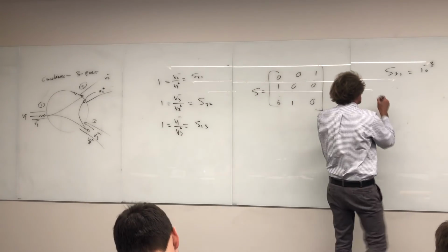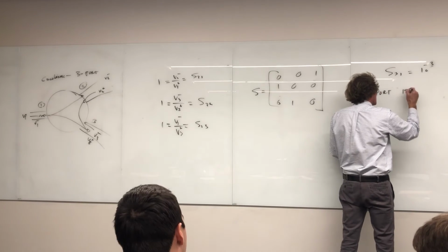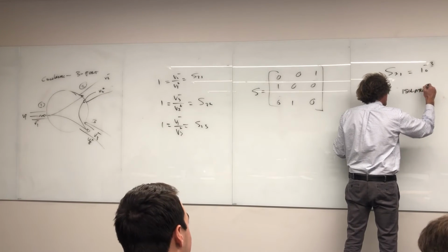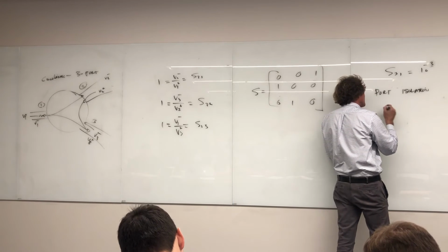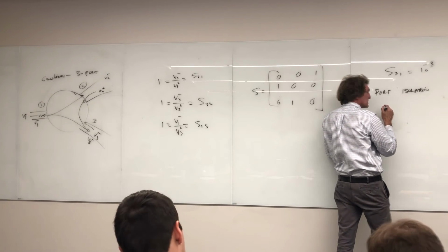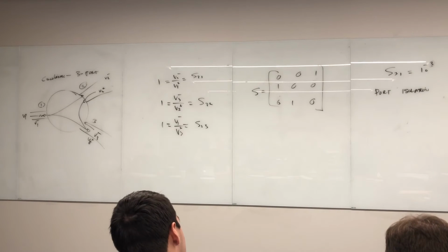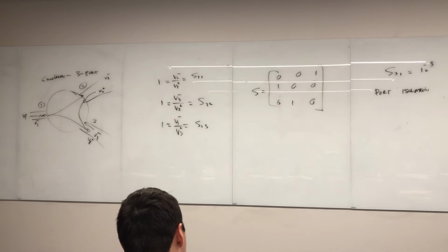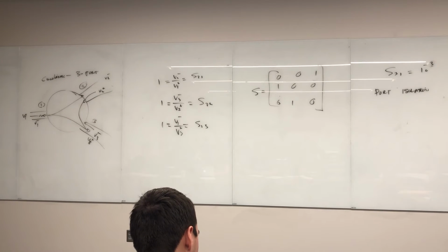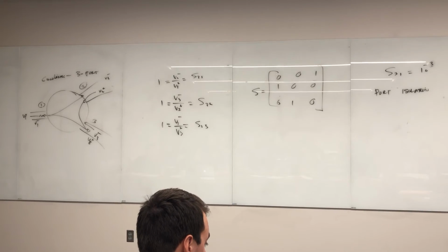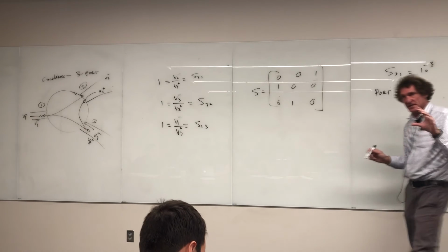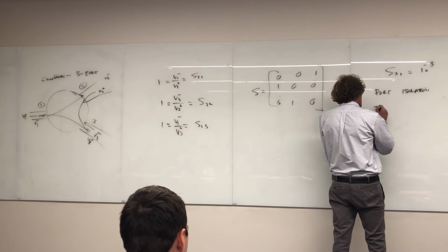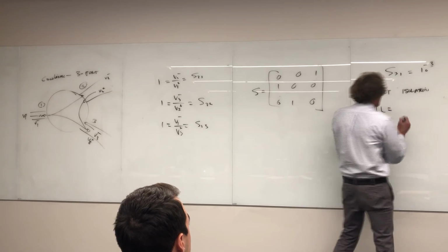Well, when they talk about port isolation, and this is true for anything really, any kind of port isolation, I call it port isolation. In his book, he's going to use different terminology. He uses insertion loss and then isolation, but really almost all these in the real world are called isolation losses, and they define it as the isolation loss, and it's always the port number.